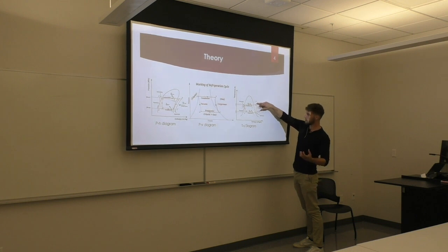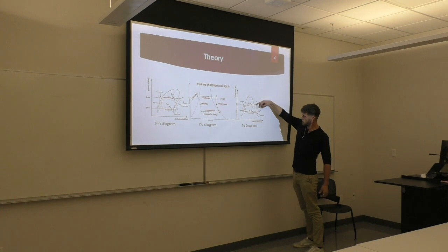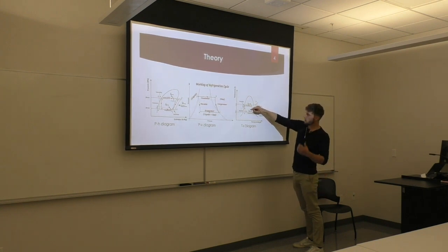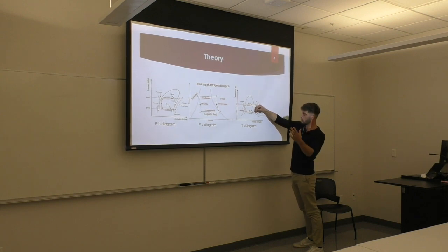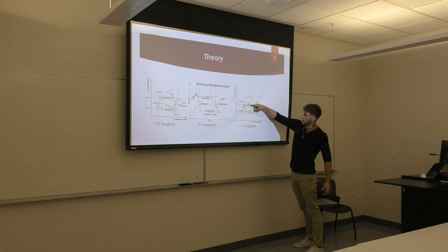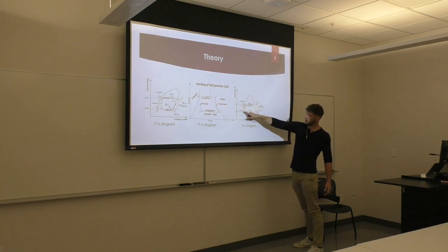So you have this gas that's superheated and wants to cool off. As it goes through the condenser, it works its way through the saturated mixture, condensing, and it wants to cool off, so it's rejecting heat to its surroundings. That's your heat pump. And you work all the way from saturated mixture to almost a full liquid, or a full liquid when it goes into the expansion valve, but it's high pressure. The expansion valve lowers the pressure, and when it comes out of your expansion valve, that's the coldest your liquid's ever going to get.